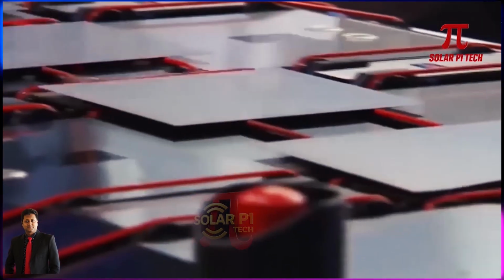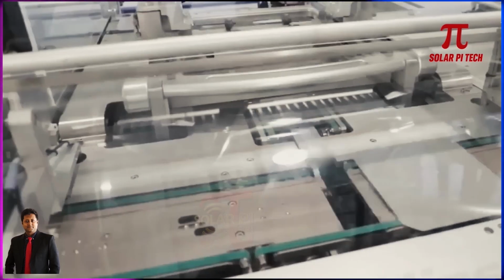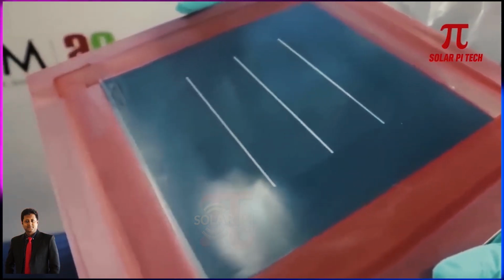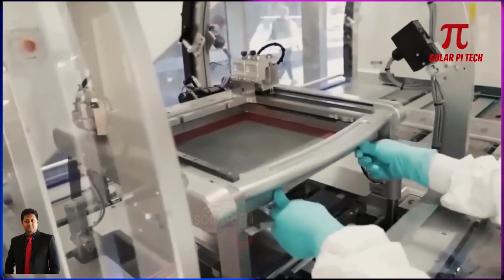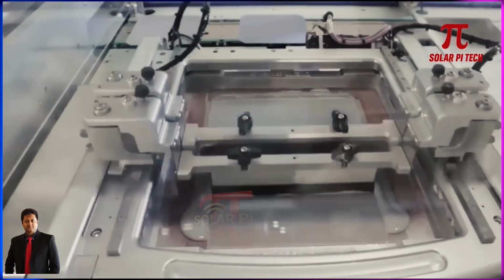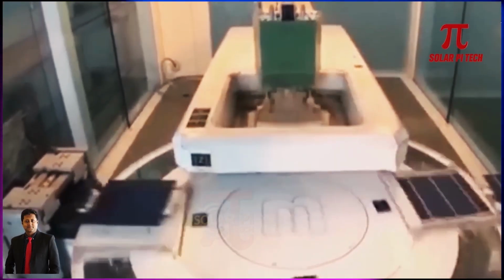All wafers are then measured by fully automated sensors and cameras, and graded according to their thickness and surface quality. In the next step, each wafer is processed into a solar cell, capable of converting sunlight into electricity. Metal conductors, typically made of silver or aluminum, are screen printed onto the wafer to create a grid-like matrix, ensuring uniform distribution of electrical current.